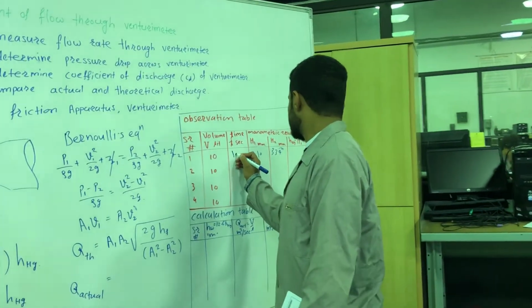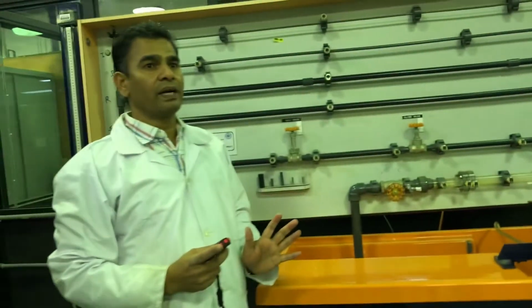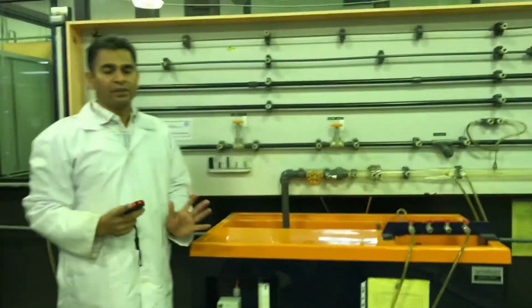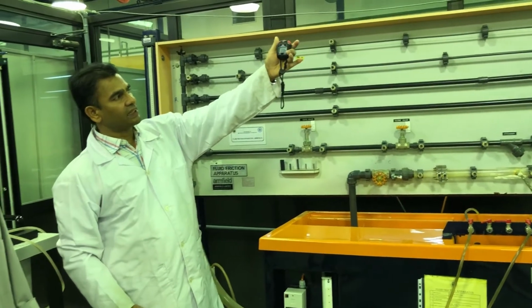Immediately open this valve. Immediately open this valve. Otherwise the motor will run without water. It will become hot. Okay. Now this first one is for reset.